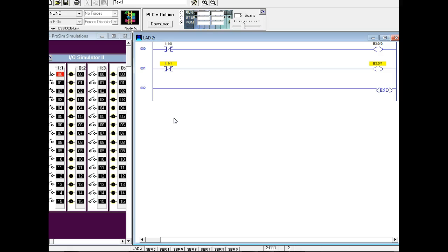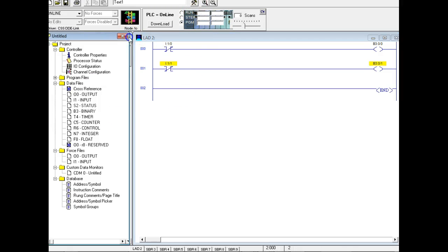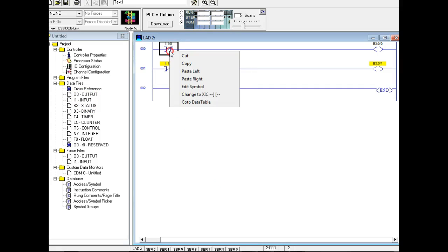Could you show Alfred the little click on it for how you tell that examining open and examining closed? Oh, you mean the actual activity? Right click on the symbol. Now you know that's examining open. Just change it to examine closed from the bottom, right here. So that's why we use normally open input symbols for normally closed contacts.